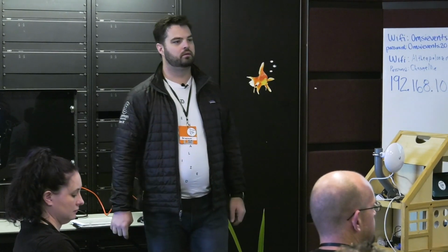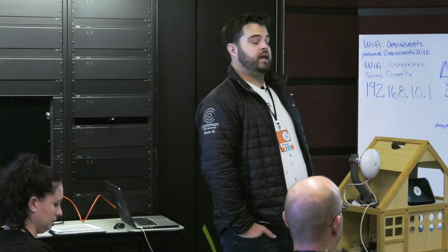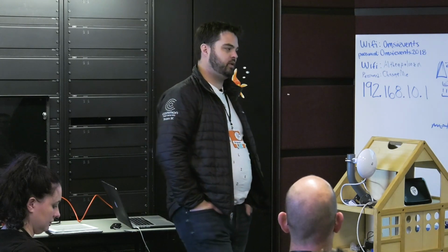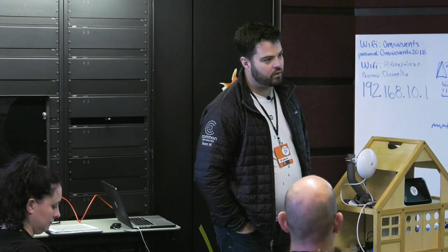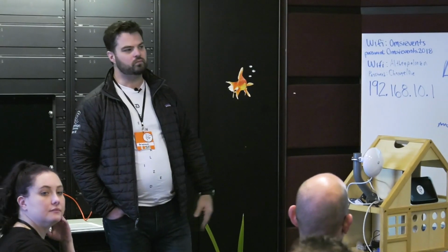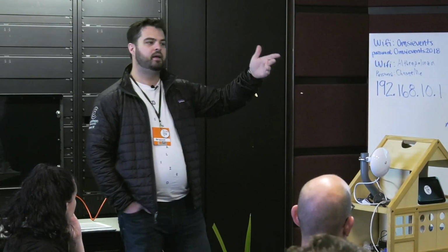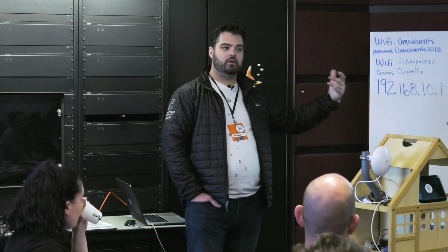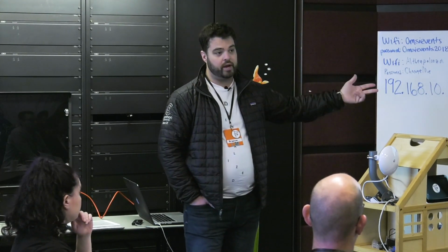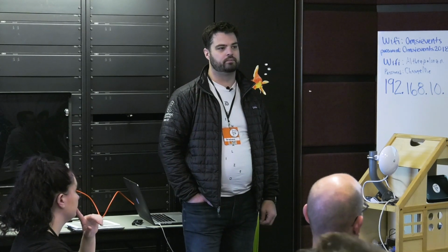Is your question, if this is like a water tower, is it hard to get power to the tower? Yeah, it can be. The question is, in the case of a water tower, can it be hard to get power there? And the answer is yes, it can. It depends on the jurisdiction. Some water towers and water tanks do already have power, maybe because they have some monitoring there, or it's in a residential area and it's easy to get. In some cases, there is no power at the water tower, and the options are to build a solar installation, which is feasible but can be expensive, or trench power there, which is also feasible but can be expensive. So, good question.